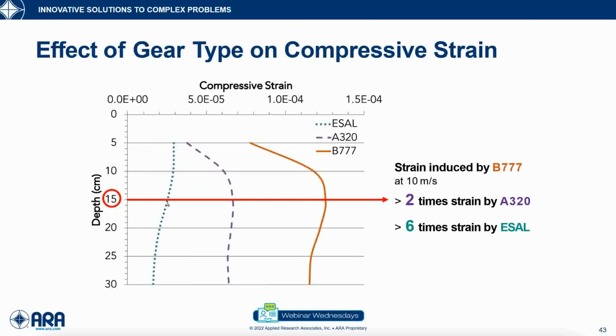So that's deep in the pavement. So the compressive stress, the compressive strain difference is not felt at the surface. It's felt deep down in the 6 inches down deep in the pavement. So I need to be careful here when I'm designing and when I'm choosing the mix for deep down.